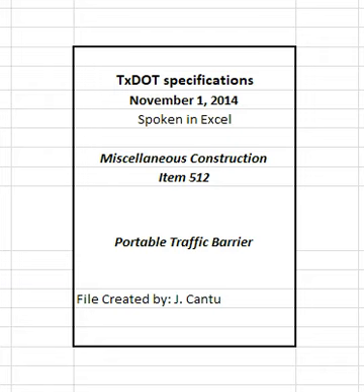Obtain assembly and installation information for the portable steel traffic barrier from the manufacturer, and provide the engineer with an installation and repair manual specific to the portable steel traffic barrier. Repair or replace all traffic barrier or connecting hardware damaged by the contractor's operations at the contractor's expense. Repair or replace any pavement damaged in the process of installing, moving, or removing barrier sections at the contractor's expense.